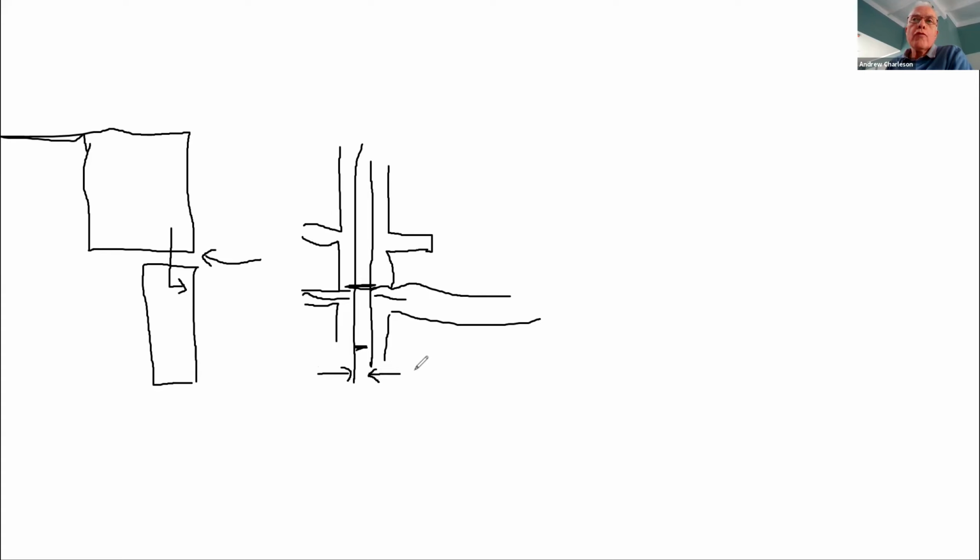And so you've got to ask your structural engineer what the width of that gap must be. Like for buildings that are, say, 5 stories high, the width of this gap might be in the order of, say, 30 centimeters.